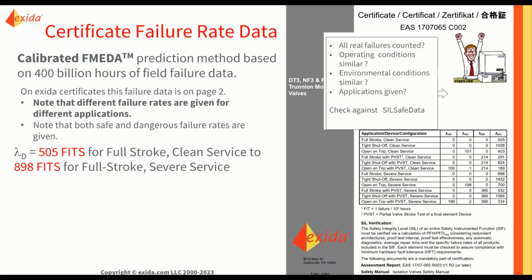Are all real failures counted? Yes, they are in the calibrated FMEDA method because the calibration is based on real field failure data. It does give you separate data for operating conditions, operational environments, and applications. And you can see that. There's full stroke, tight shut off, or open on trip.